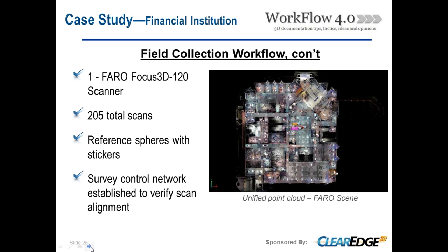It was interesting. There was a question earlier with Mike's presentation relative to how to reestablish targets. We've developed our own stickers, which are used in conjunction with our spheres, and those are pretty important on this project because we came back over 3 different times, and since we couldn't scan the facility at one time and flow freely through the space, it was really essential that we could reestablish our targeting, and couldn't rely on overlapping scans. And then lastly, of course, we did establish a small survey control network, which was utilized to verify our final scan alignment.